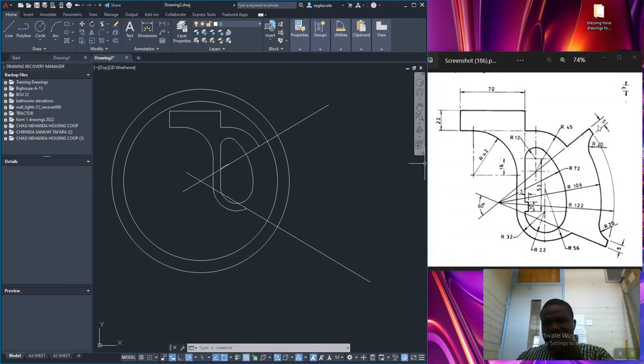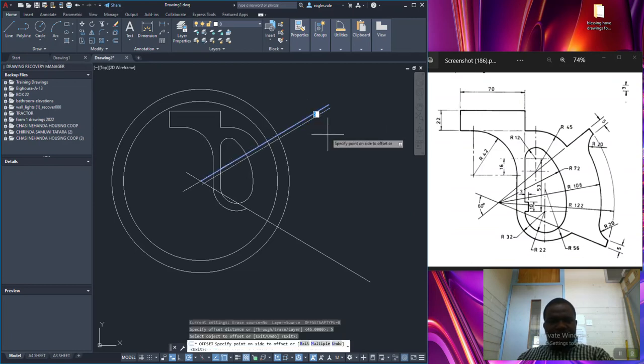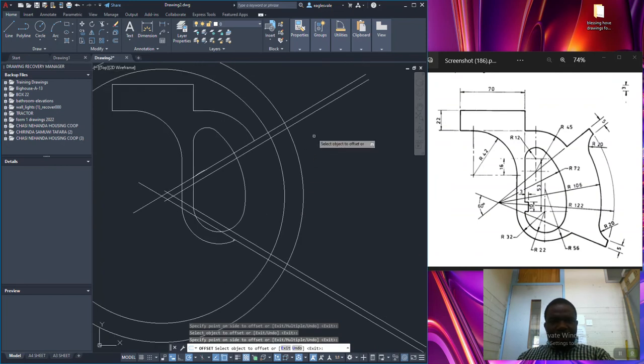We also have a distance here which is 5. Before we put the transverse radius circle, we have 5 again here, so we need to make offsets 5 getting inside from these positions. So it's easy, offset, the distance is 5, press enter, this one goes inside, this one goes inside. So it means we are in a position to trim unnecessary lines here.